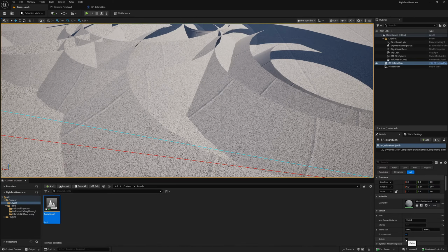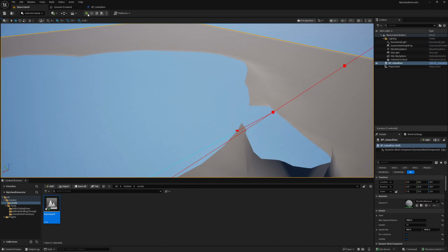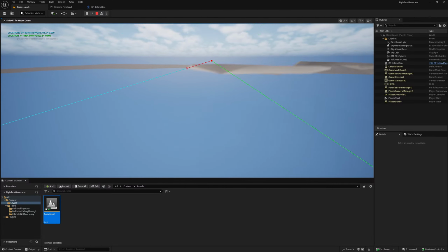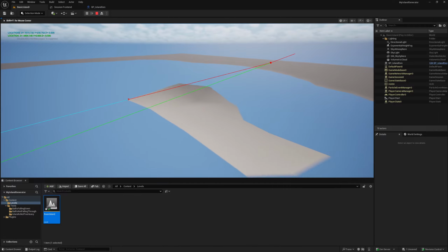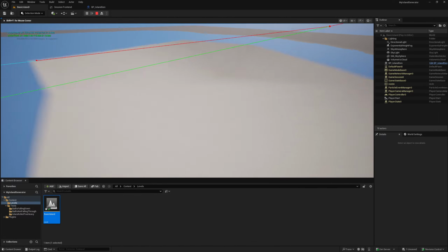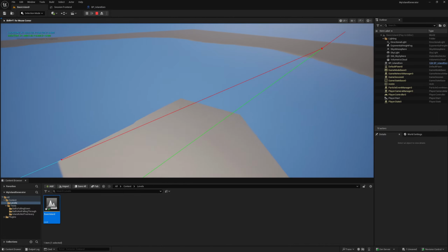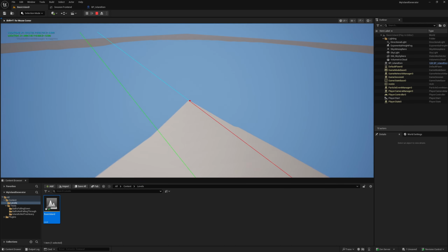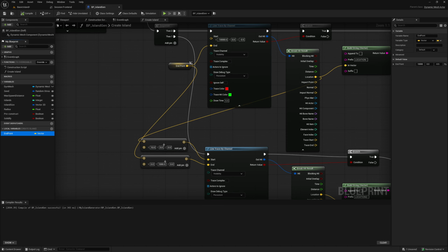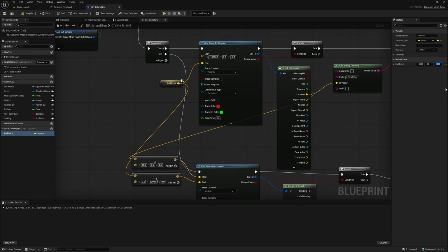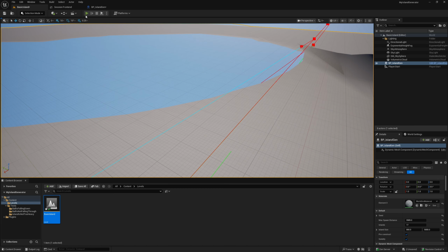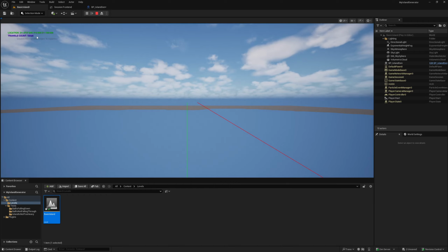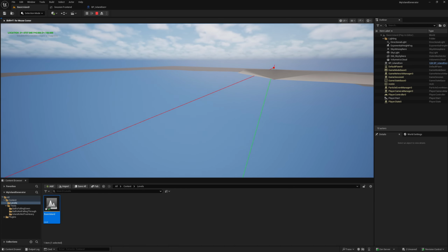What happens if I solidify? When I run, I still have 2 hits. I expected 1. Okay, because of this dip on the surface of the island, I got extra hits. Well, it's working, but is it too high? What if I lower the trace, using minus 100 instead of minus 0.5 to get below the dip? Okay, only 1 hit then.